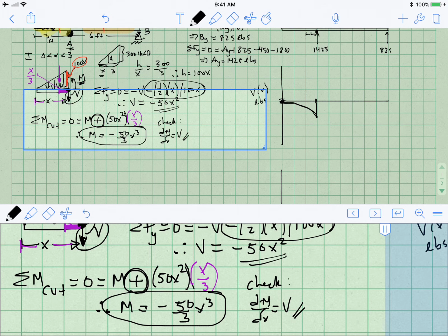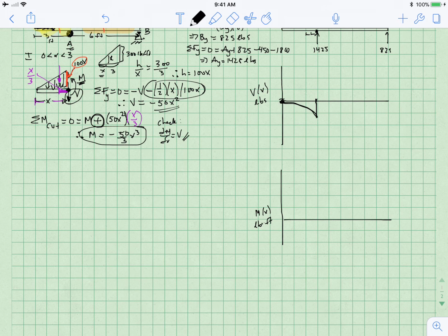All right, so over here on my diagram, if I start to plot the moment curve, I get a curve that drops down to, what is that, about 9 times 450. Yeah, it goes down to minus 450. And it curves, so it's doing something like that. That value is minus 450. So that's what's going on in region 1.